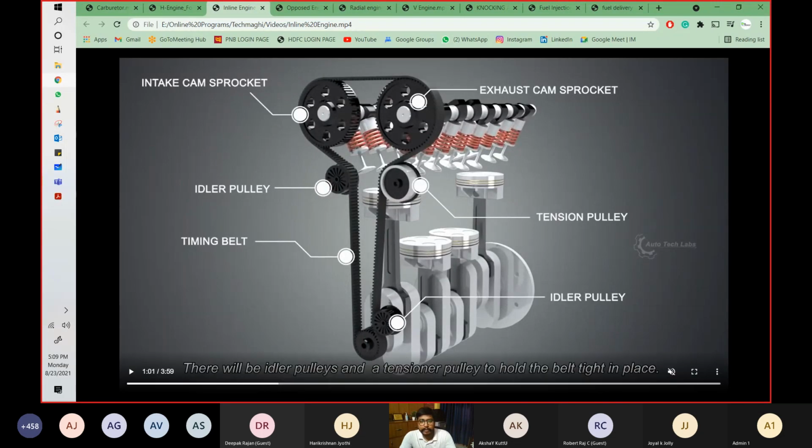So what is the timing arrangement or timing system? The timing system is designed for this particular crankshaft, for what period of time and exactly when any particular valve is to open. So let's say cylinder 1 valve is to open. When does it need to be opened? This timing belt or timing system is designed for the operation of these camshafts and for these valves.